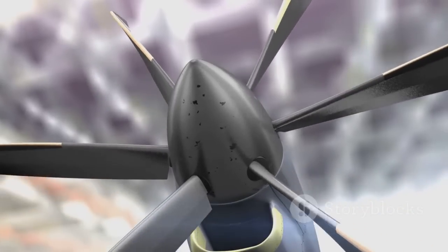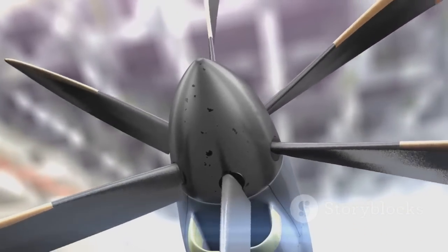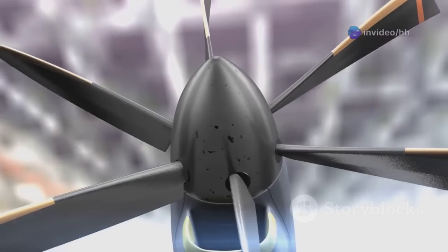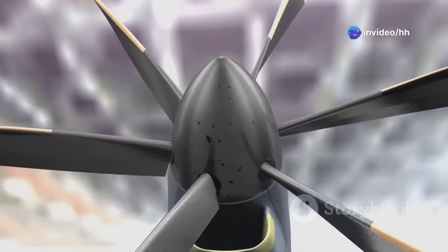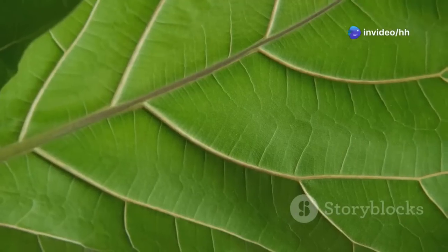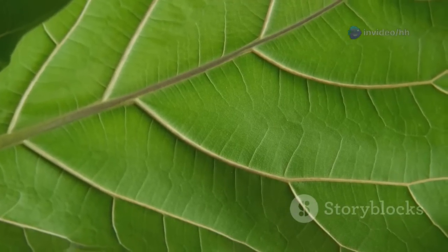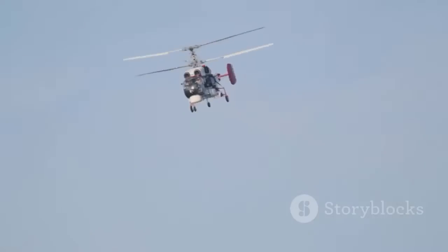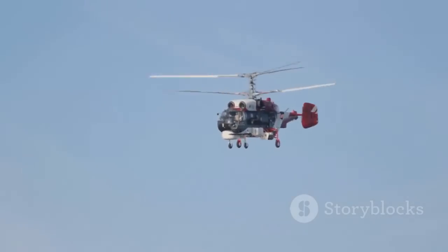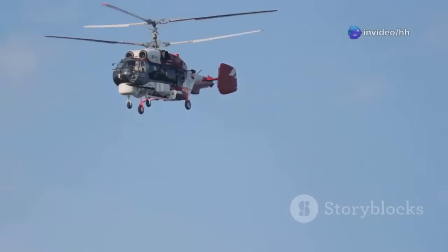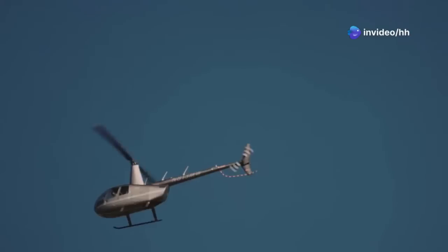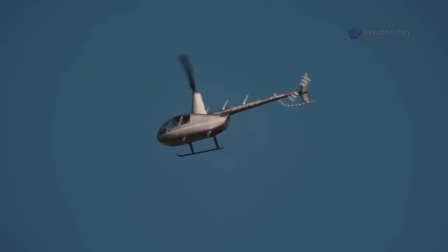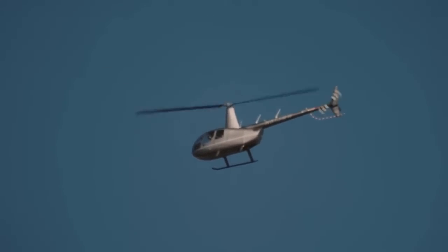Symmetrical airfoils. These airfoils, as their name suggests, are the same shape on the top and bottom. This symmetry allows for consistent performance in both upright and inverted flight. Picture a perfectly symmetrical leaf. Just like this leaf, symmetrical airfoils are balanced and stable. They produce lift but are mainly used in applications where stable flight at various angles is crucial, like helicopter tail rotors. This stability is essential for maintaining control in diverse flight conditions.